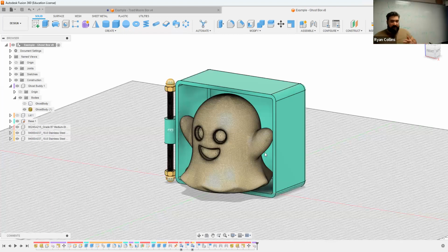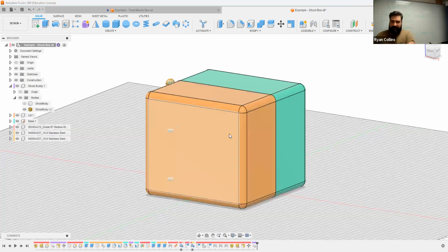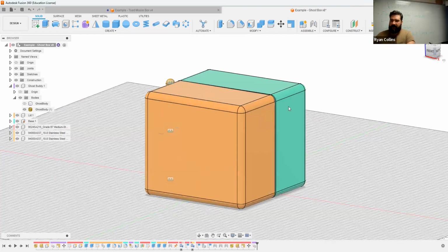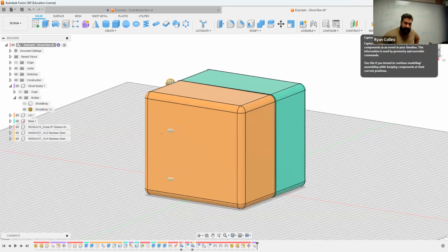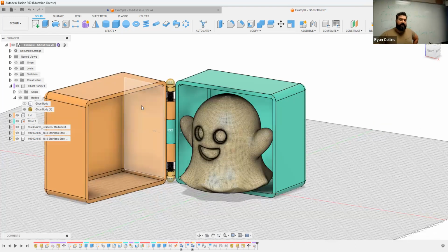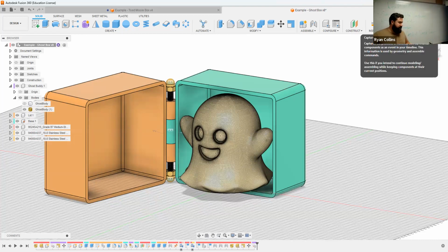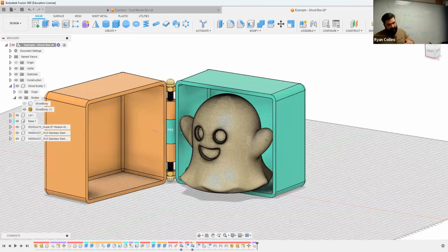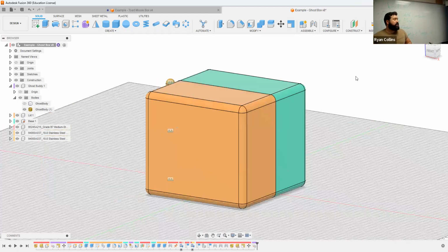All right, back to our little blueberry friend. So where we left off, we had the basic stuff down. We had some modeling done. We have got the hinge working and all that. Again, remember, if you make movements, the icon at the upper right-hand of the screen will come in if you want to capture position, meaning if you wanted to model this closed and then leave the example model open or in its current position, you would use the capture position icon here. And again, you mouse over it, it tells you what it is, or revert puts it back to where it originally was, not even to where you just left it. It will put it back to its original location and orientation.